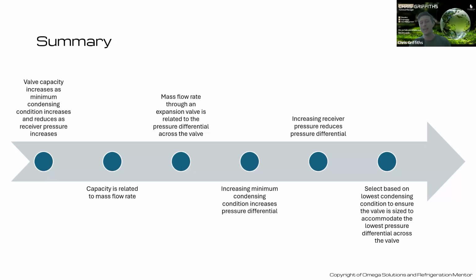There's a lot more in depth we can go into, and how it plays into a part in terms of what if you have a very low load condition, but a very, very, very high load condition as well. How do we balance that? We need to then have multiple valves. How do we balance multiple valves on the system as well? The control strategy for that. If you have affecting multiple gas cooler circuits as well, how do we achieve that?